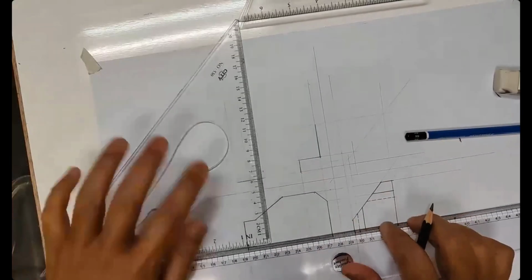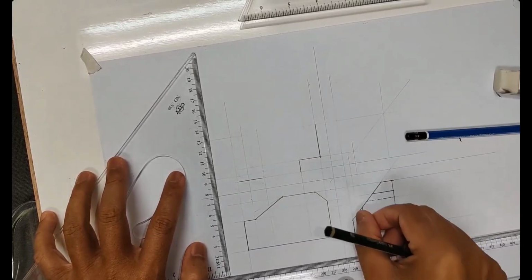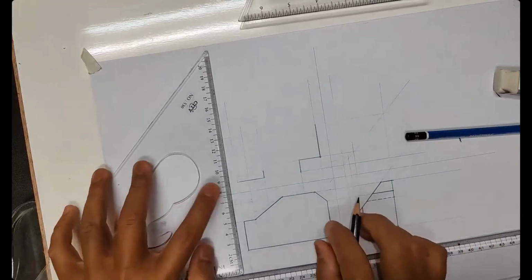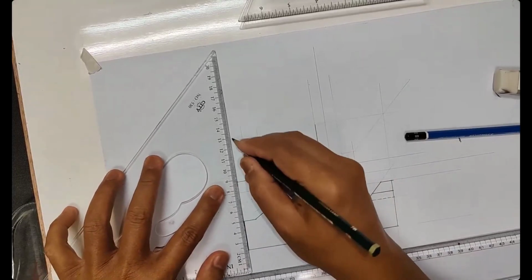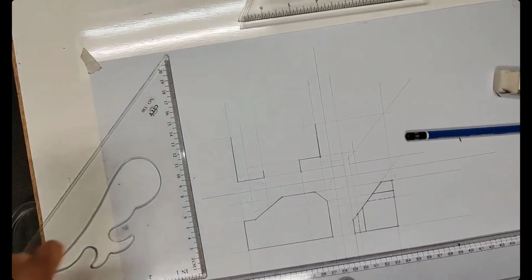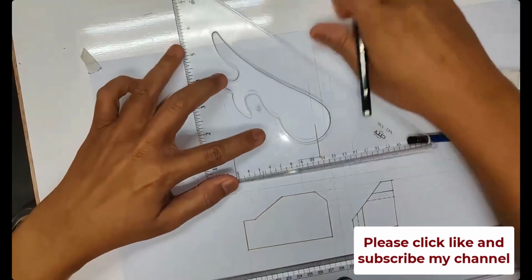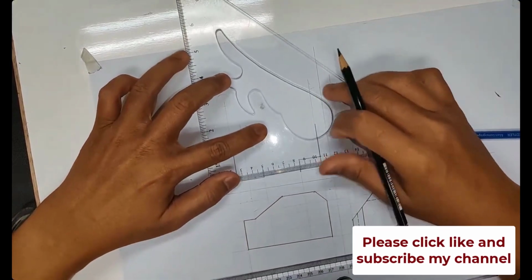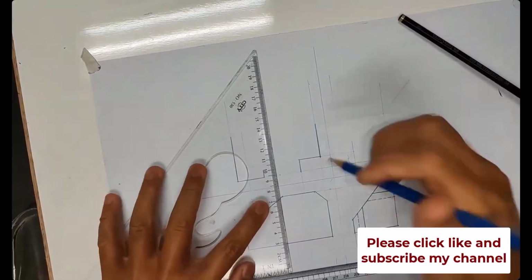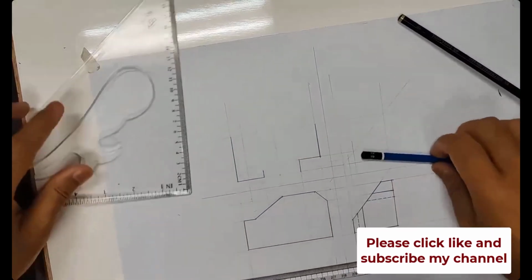So this is what we already have, line 5. Remember earlier, the side view already has the cutting of 5 units there. So we already have the profile here, up until here, and at the end up until the top. So this will be the outline. Then it will have a depth of 5, right? What is the width there? The width is 50, so measure from here. The width is 15, so 15 is here. Using your 4H, you bring it down to assist you to do the profile on the front view. So the cutting slot will be here.